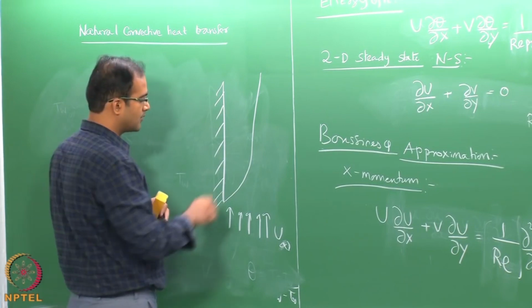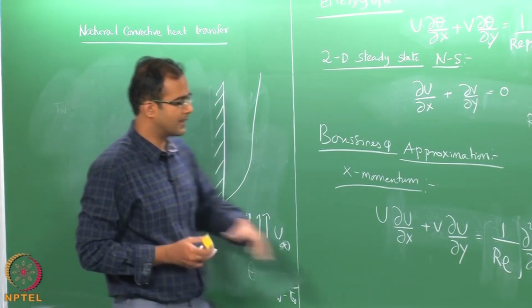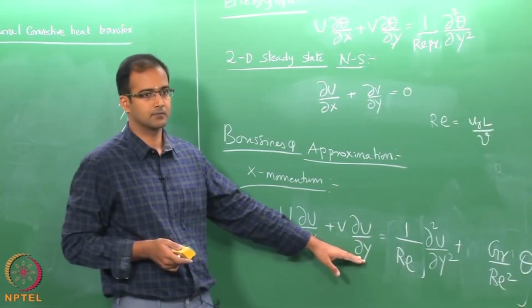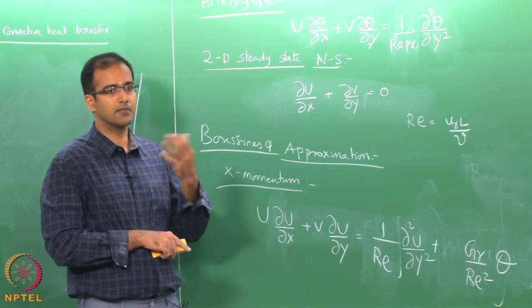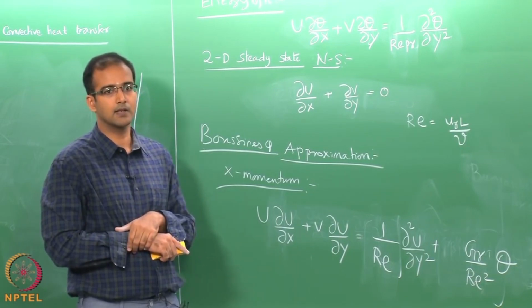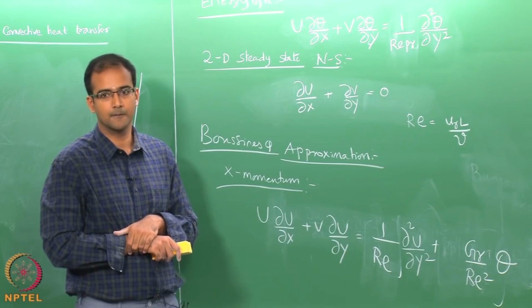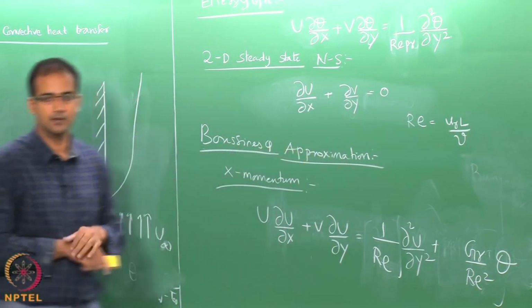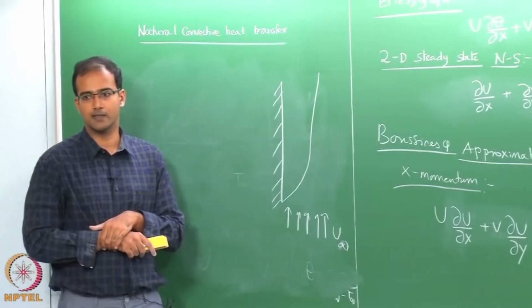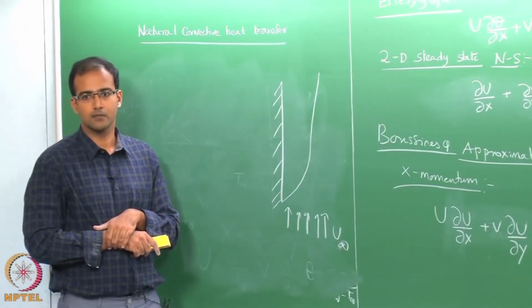Now, this is a combined effect of both your forced convection and natural convection. Okay. So, in such a case the same equations are valid, but your u reference can actually be u infinity, because even if you do not have any temperature difference, the forced convective boundary layer will still exist. Okay.